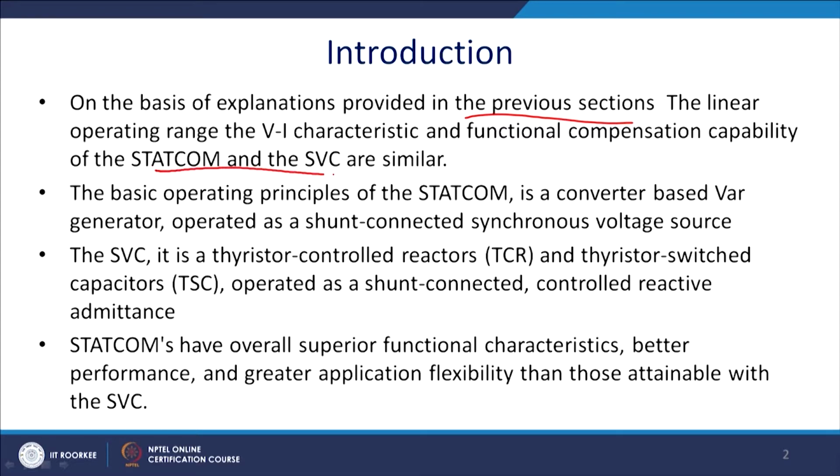We can use STATCOM as well as SVC both, but there are ifs and buts. The basic operation principle of the STATCOM is a converter based var generator acting as a shunt connected synchronous voltage source. Essentially, it is a voltage source and SVC is actually an impedance. So, there is a basic philosophical difference between these two.